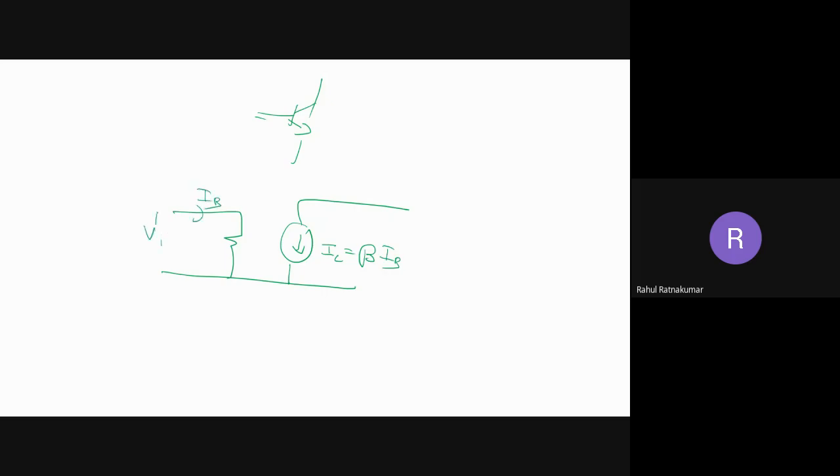Okay, so that much, once again explained. In order to explain a complicated three-terminal device, a transistor or amplifier, we make a small signal or simplified model like this, with a resistance and a simple current source, all things which we know, and we just write the behavior of the transistor here, the beta times IB, where IB comes from the input voltage VI or VB here, and this is the IC, fine, and this V output is taken across the output. So this is a simplified model of the transistor, right?